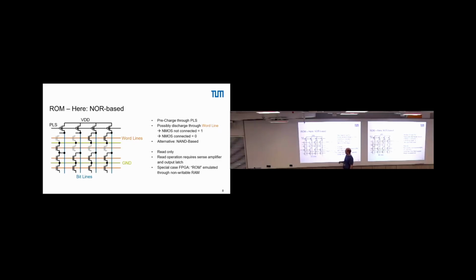Now let's go maybe for this word line here. If we do the same thing, we pre-charge this to VDD, which is 1, enable the word line, then this here is unconnected, right? There's no connection to ground at that point.